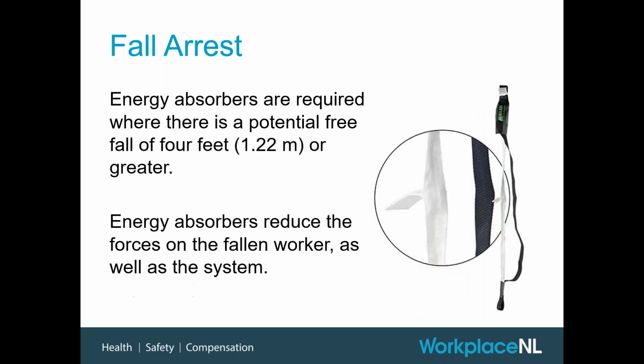Okay, so continuing on with our discussion about fall arrest, there's really a lot more involved with planning with a fall arrest system versus a restraint system. One thing in particular to consider is energy absorbers. These are sometimes called shock absorbers or shock packs. These are required wherever there's a potential free fall of more than 4 feet.